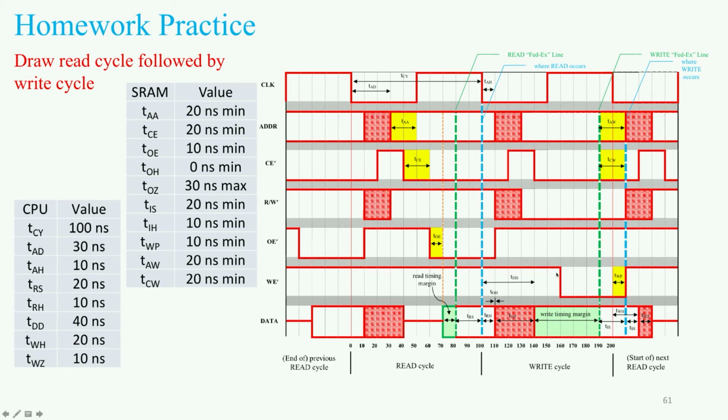Then when we got into the write operation, when the clock transitioned to the high state, the fact that the read-write bit is low and the clock is in the high state means that the write enable bit will end up being asserted. But it doesn't happen immediately at the edge, again, because of glue logic. That signal persists throughout the back half of this cycle, and we'll look at what happens on the other side when we get over here.